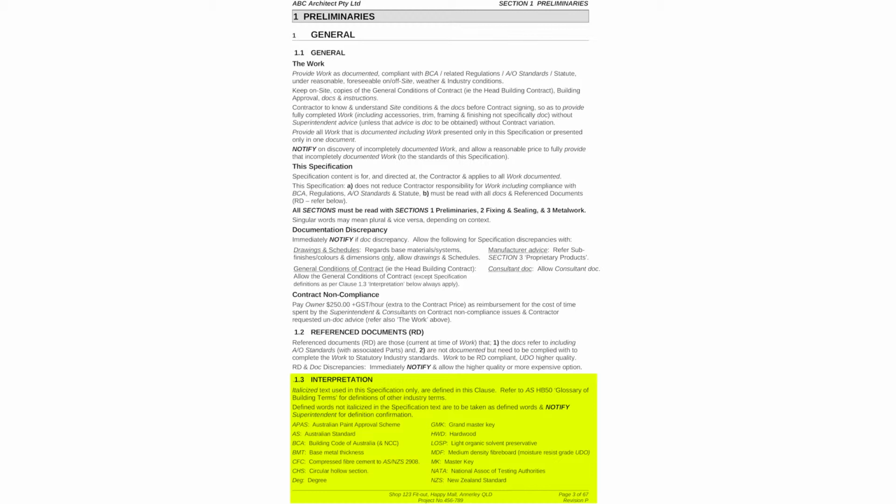Now for some important definitions to show how carefully this has been planned. Remember, the aim of this spec is minimal or no disputes. Advice is written, not verbal. Consultants draft documentation. Engineers are contractor employed. Remember, these definitions are only for the spec. Documents and drawings are contract documents only. Exposed to view is that visible at practical completion without disassembly, such as inside cabinets, which helps define extent of finishes. External, this definition finally eliminates all misinterpretations of this word.